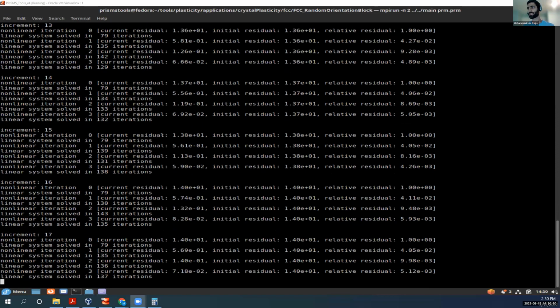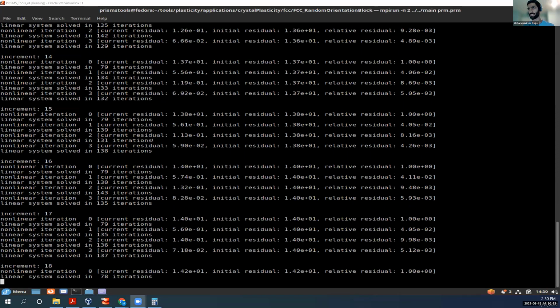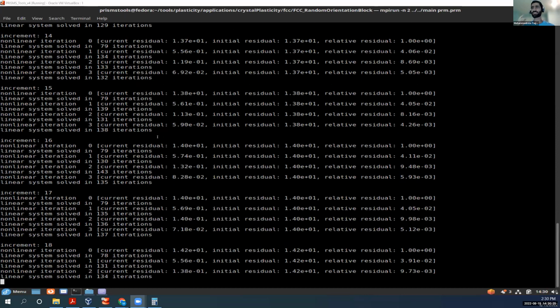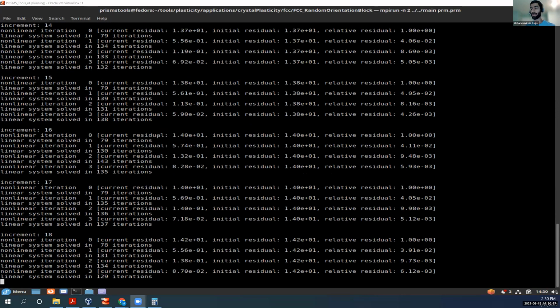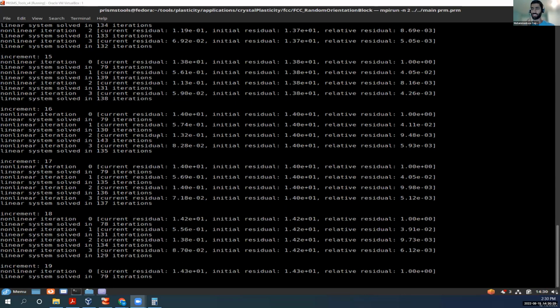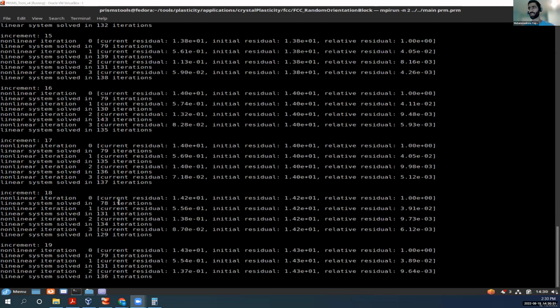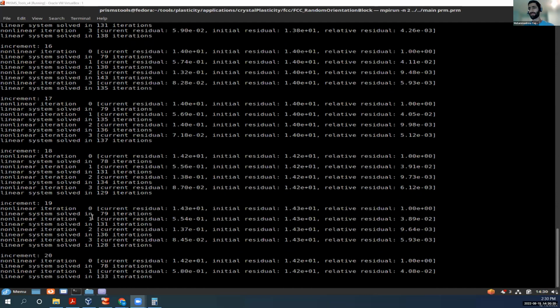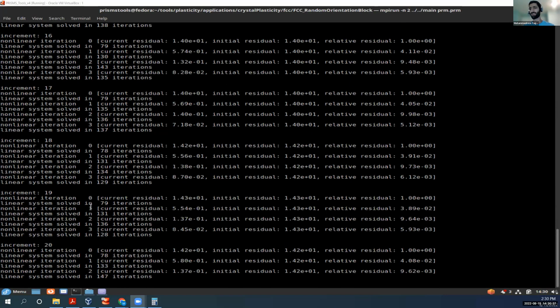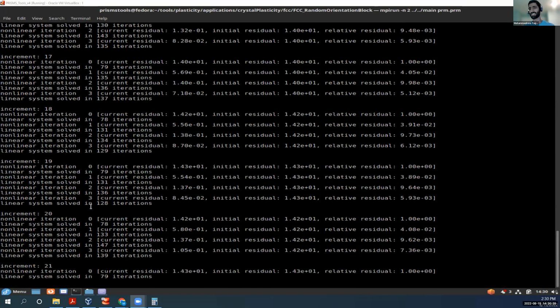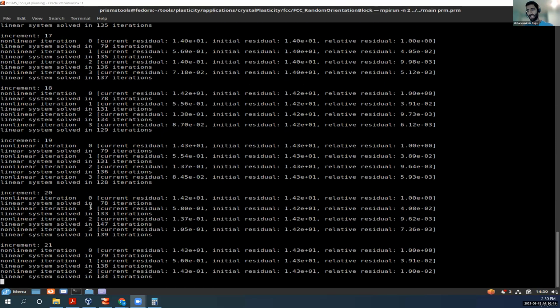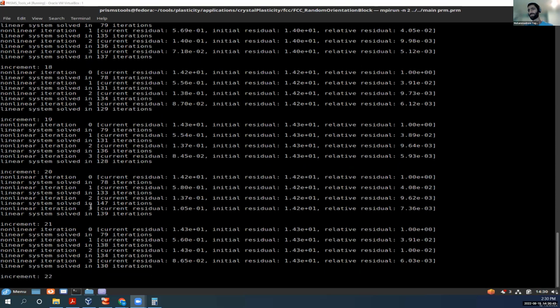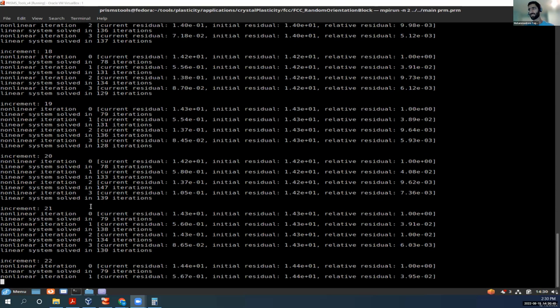So if you delete the grain ID, how can you visualize it? ParaView. Yep. You can visualize it after you finish the simulation or partway through the simulation, like what we are doing right now. If you set the skip output for every increment, you actually get to see the visualization at those time steps, and you could see that the element has been deleted already.